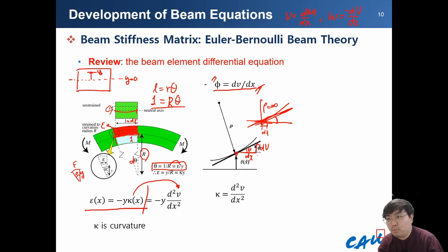And then we need one more thing. For the movement in theta, maybe from the previous relationship, but for convenience I'm going to change the relationship. First theta may be equal to 0. However, due to the deformation, theta will change to d theta. So that means d theta over dx is also equal to the curvature, y.